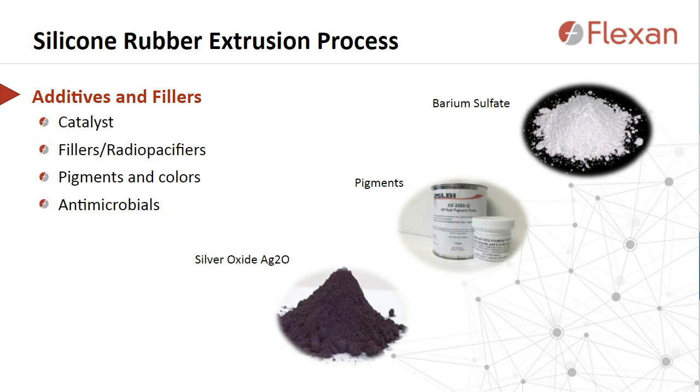Radiopacifiers can be added to allow the silicone device to be visible when x-rayed. Pigments or colors: in today's competitive landscape, having the ability to customize the appearance of your device can help it stand out and improve brand recognition. Antimicrobials are becoming more and more relevant to prevent infection. With the introduction of any additives, care must be taken in their selection, such that they do not potentially inhibit the curing or otherwise negatively affect the performance of the silicone.